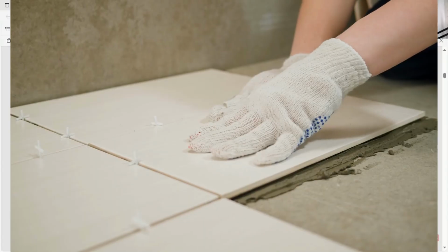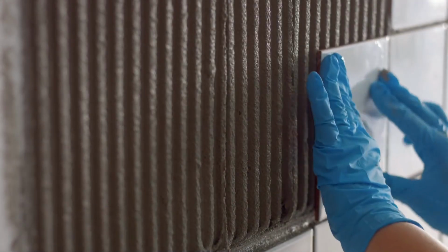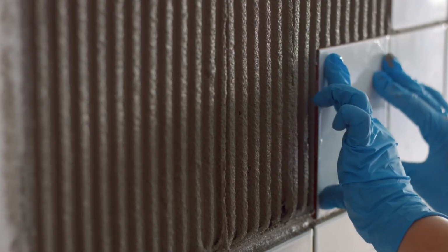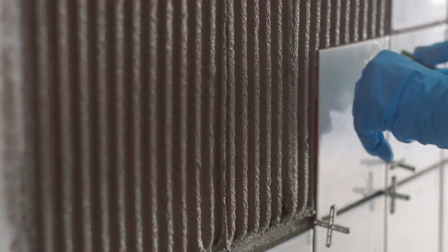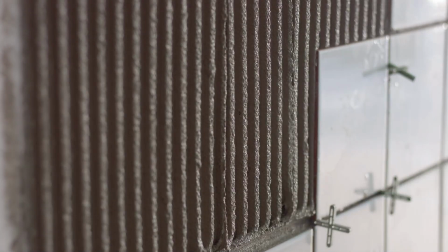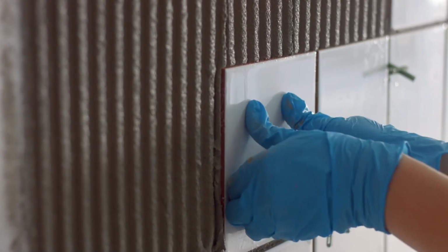Now another thing is open time. Why do you want to know? Because this is a criterion for the selection of the tiles adhesive. What is open time? The maximum time interval after application at which tiles can be embedded in the applied adhesive. That means after preparation of the adhesive, how much time it will be workable. So that is the open time. It may be 20 minutes, it may be 30 minutes. Depending upon that, the tiles adhesive or the tile types will be different.